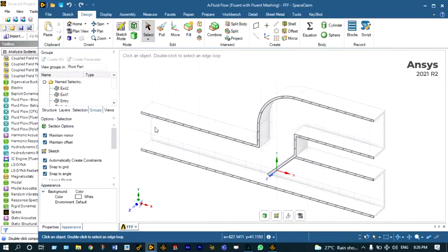This is actually a wind tunnel having two exits. From fluid mechanics, we know that the mass flow rate will be more at the bottommost position, and at the uppermost position it will be less. So with a view to having an equal flow rate, we have provided one baffle with an angle of 45 degrees with the vertical axis.